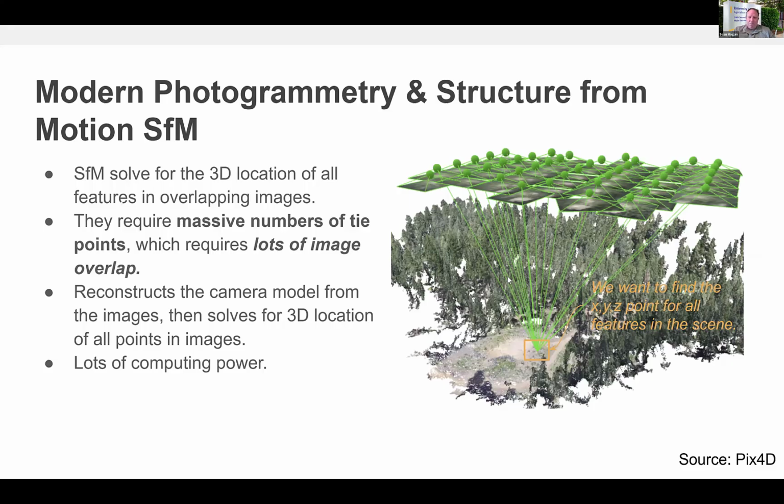This is just a screen capture from one of my projects from Pix4D. I can bring that up here shortly just as an example of how photogrammetry applications work. In this case, this is a forest up in El Dorado County with a set of images, and 57 of those images could see the same X, Y, and Z, X and Y being the easting and northing, and Z being the altitude of the position. And with that, you can reconstruct the surfaces. This does require a lot of computing power, though, I might mention.